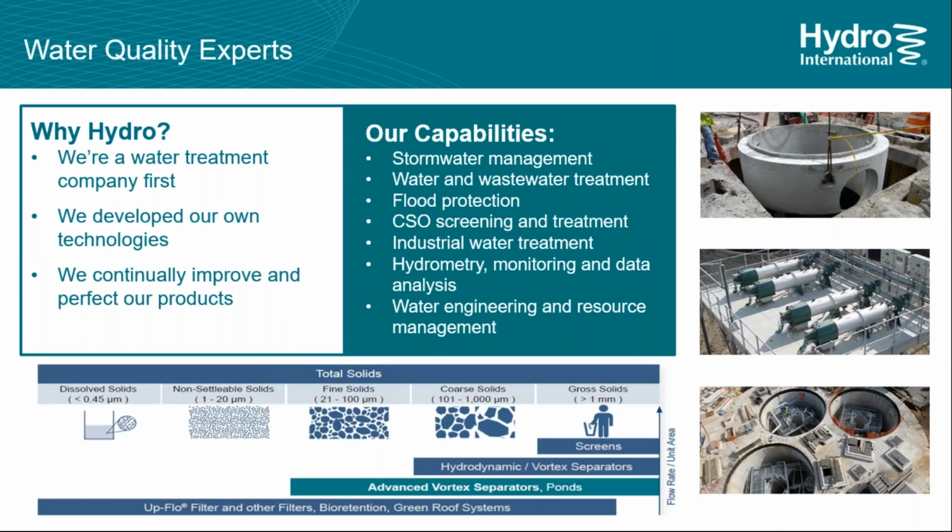We're using filters when we get below that 50 micron threshold. And really, why the filters are required is because that sediment will no longer fall to the sump through gravity. So we can't use gravity alone for the removal portion of it. So that's when we're having to filter.